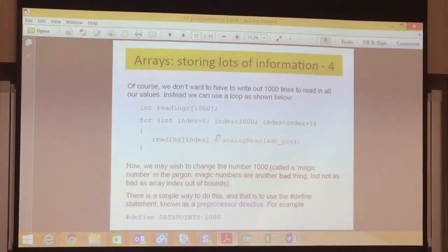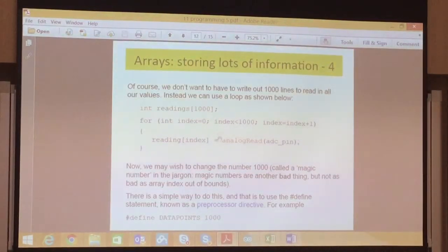In this way, you have already saved your 1000 readings into an array. And the analog reading is very fast. So if you save all the data in here, it takes very little time to wait. So you can capture all the transitions for the switch bounce.